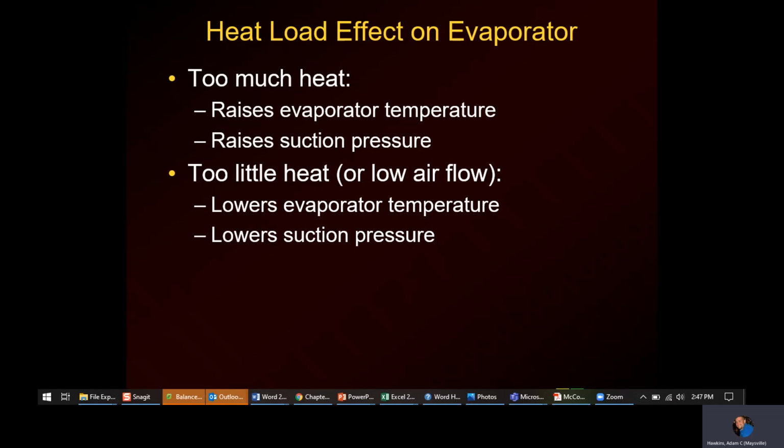And then I would look at my refrigerant pressures and say, okay, I'm still going to go by my indoor minus 35. So if it's 85 and I subtract 35, I'm maintaining that TD. Now I'm looking for a 55 degree saturation temp instead of a 45.